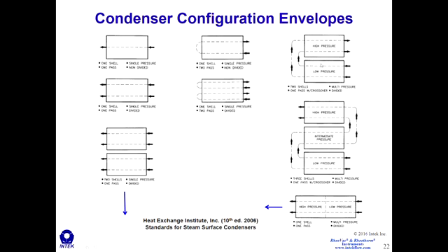These shells could have different pressure compartments. Here the water comes in cold, warms up as it goes through the low pressure shell, and enters the higher pressure shell. There are low pressure turbines tied to each of these, but they operate at a higher pressure and a lower pressure. You can also have multiple shells, up to 3 or more, or a single shell with multiple pressure zones in it, like this.